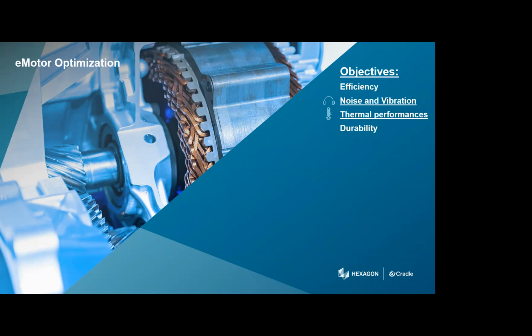Having a great battery system but an inefficient motor is not going to help us much. Noise and vibration, and we will see just later why. Thermal performance, since we don't want to have to stop our motor to let it cool down. And finally, durability, which is always a very important concern about the reliability of our vehicle. The constraints will be around development and production cost, basically, development time, packaging, and manufacturing.